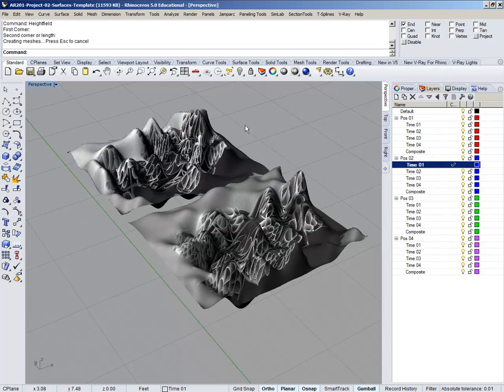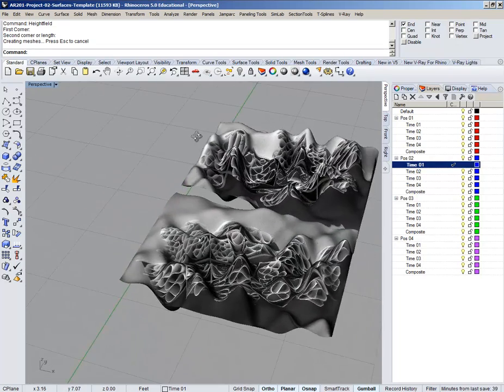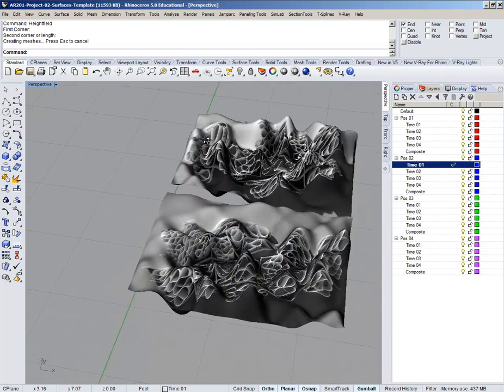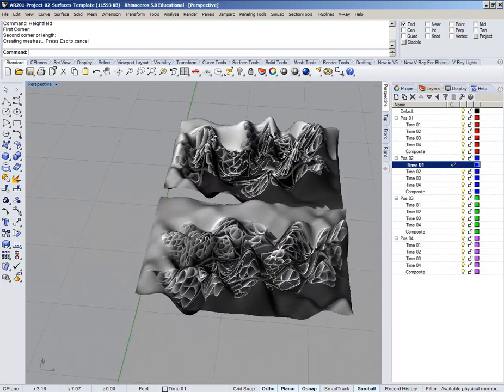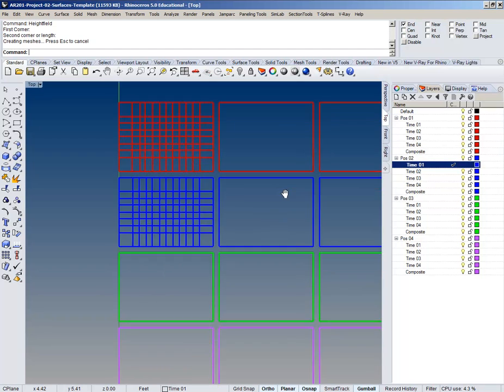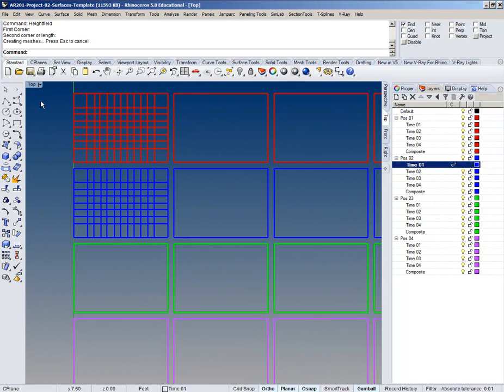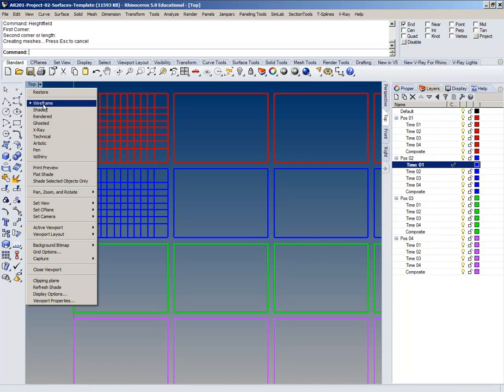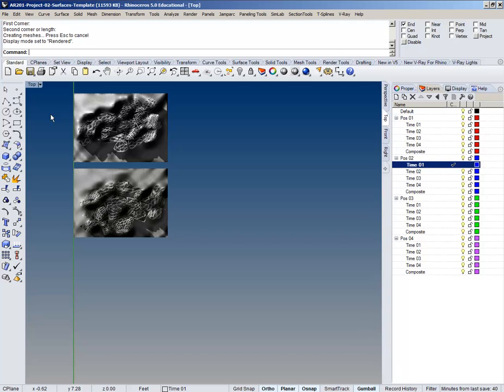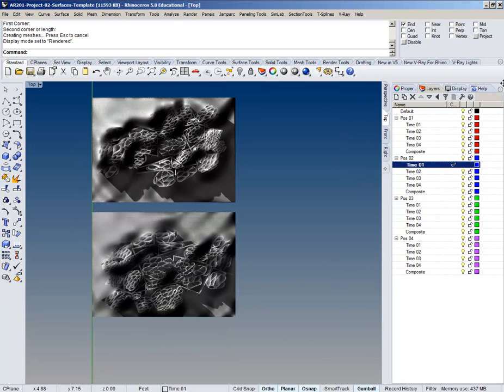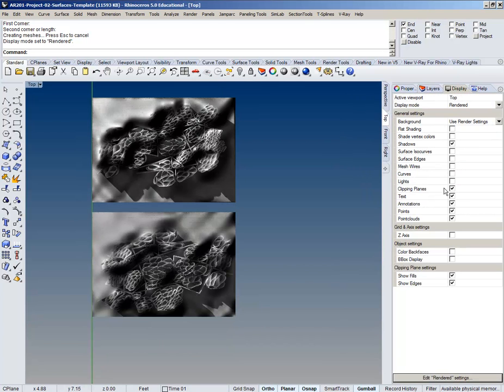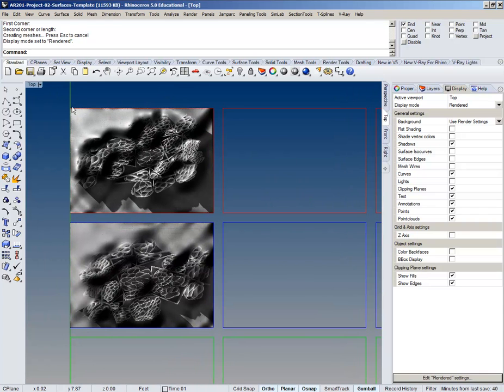Otherwise in Rhino, you're using the left mouse to select objects and you're using the right mouse for camera controls. So in my perspective view, I'm orbiting with my right mouse. When I'm in the top view, that same right does this. And this is the same exact model. I'm just changing the preview settings up here. So I'm looking at it in wireframe, but it would look the same as if I changed it to rendered, right? The render doesn't tend to show the curves unless I change my displays in this display panel to the right. But you'll see as this model gets bigger and bigger, you'll probably want to keep it in the wireframe menu up here because it's the faster method.